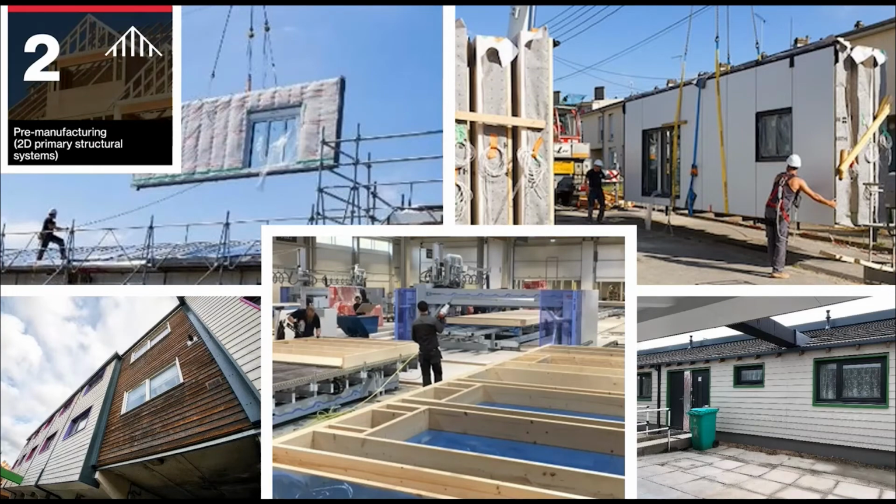Category 2 is the creation of 2D panelised and framing systems away from site that are assembled on site to improve the structure of the building. There's a range in the extent of pre-manufacture. So three types, and these are based on the amount of completeness of the panel system. So 2A is the frame only, and typically these are walls, floors, roofs and stairs. Type 2B is the frame plus insulation. And type 2C is the same as 2B, but also includes doors, windows and external cladding, all added in the factory. Typical systems use light gauge steel and timber frame.